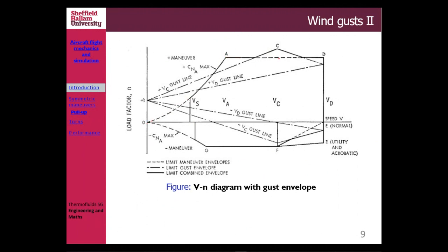If you follow that, there's point A, point D, point E, point F, point G, and go back to here. That is your standard from before. This is limited by V-stall. Remember that you're not able to fly at or below V-stall. Then your load factor, or VN diagram, is initially in the form like that, right? But adding the gust load,